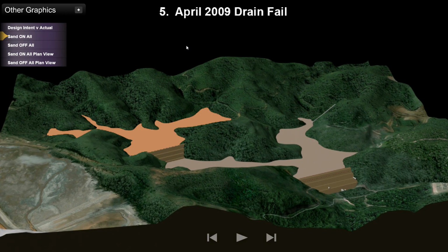The idea was that there are two types of tailings that come out of the dam. One is sand, which is just sand and water, which were intended to be stored behind this lower dam. And then there's another material called slimes, which is a clay mix, and it's very slippery. It's just like a very wet clay. The problem is that it doesn't drain. It just stays kind of gooey and slimy and slippery, and hence the name slimes.